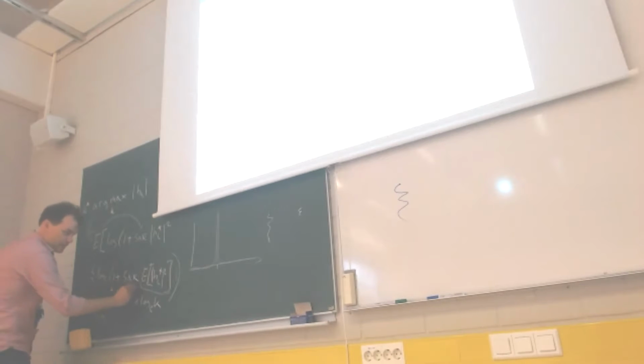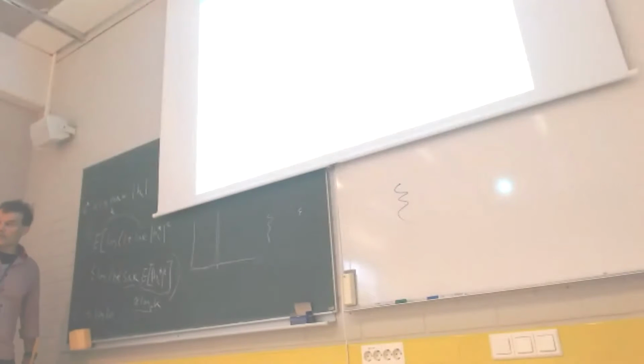Then, assuming this becomes large, we can just remove the 1 plus. So the capacity with this rate optimal user selection becomes approximately log SNR times log_e K, right? That is, log log K.